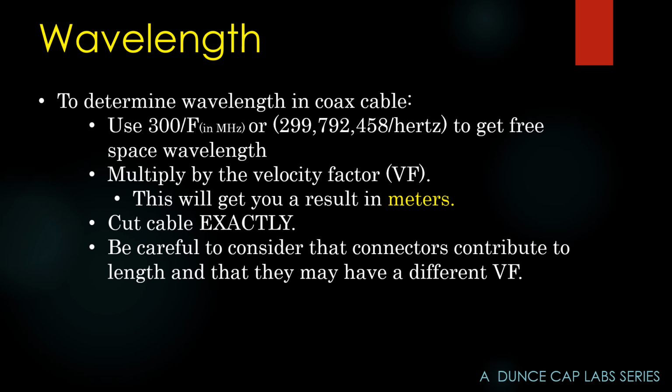Now, as to the last bullet point, the only time you've got to be so careful that you consider the contribution the connector makes is at UHF, maybe VHF. In the HF range, the line is going to be so long that the slight variation the connector gives you isn't going to matter at all.